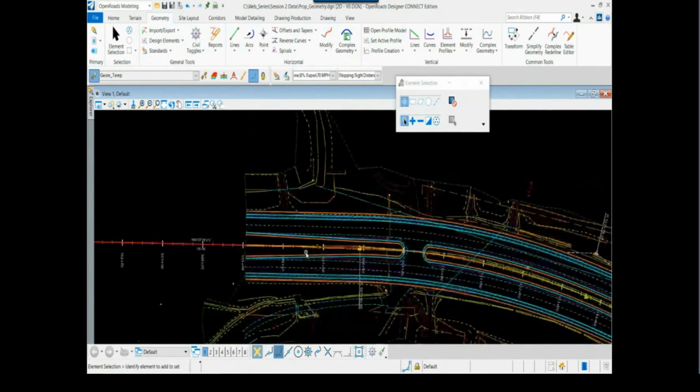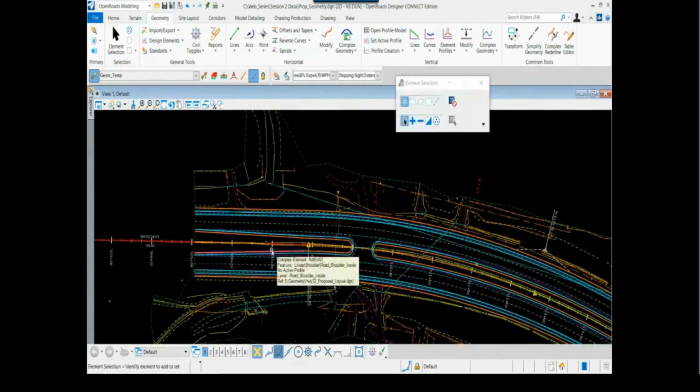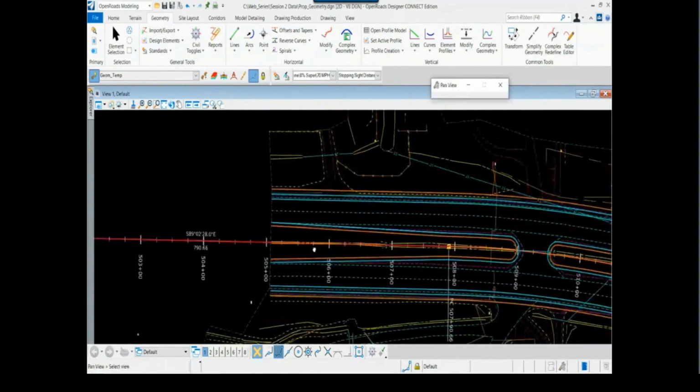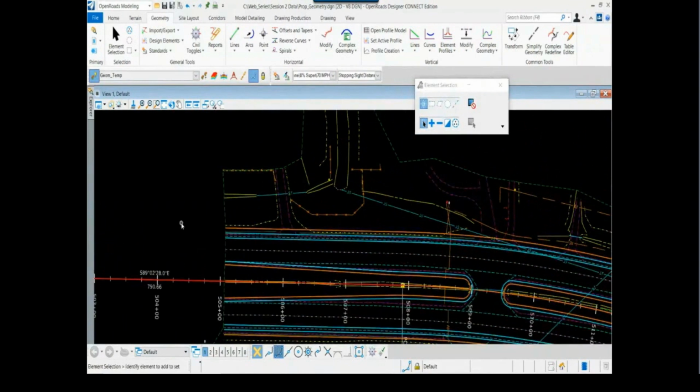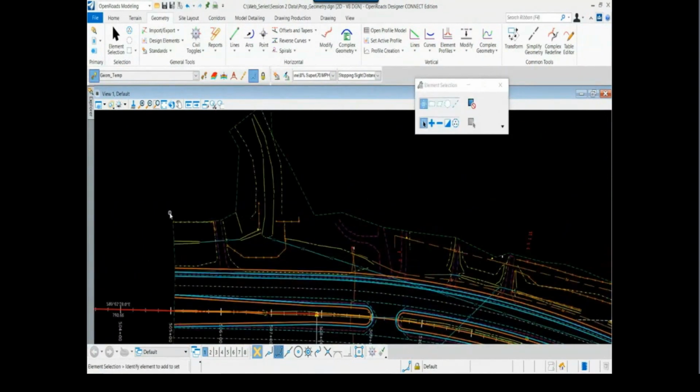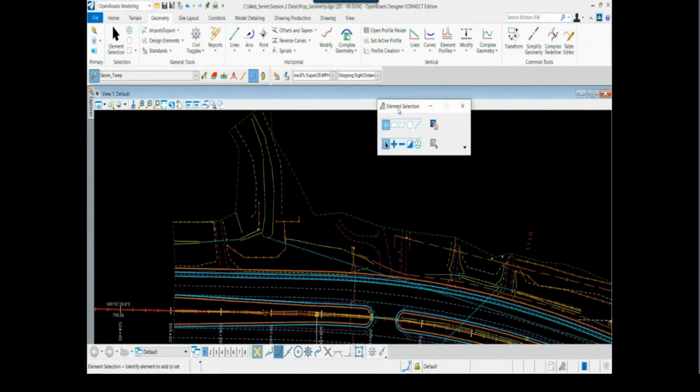How do we create the vertical alignment? What do we need to think about? And in terms of what do we need to provide for the modeling of this roadway corridor to handle and control the vertical? Well, we need to create the PGL, of course. But then you might ask yourself, all right, I want to take into account elevations and vertical aspects, but I'm in a 2D file. How does that work? Okay.